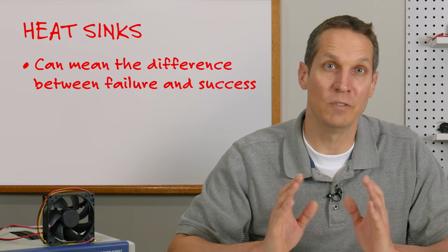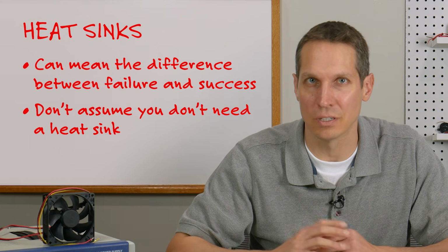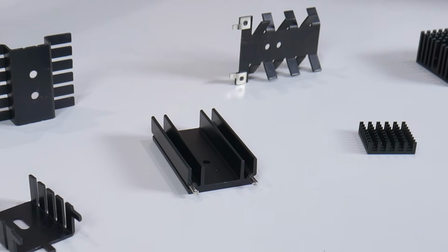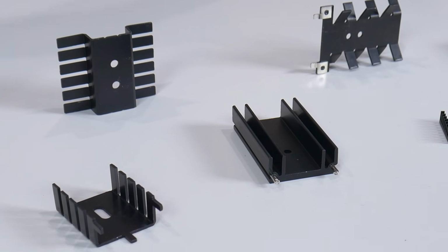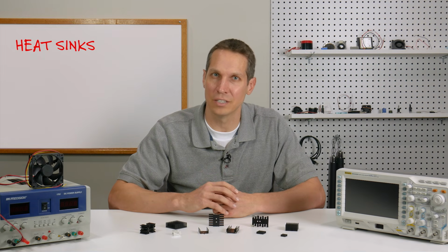Heatsinks can be the difference between failure and success, and if you don't need a heatsink, don't just make that assumption. Running the numbers on whether or not you need a heatsink is a straightforward process whose most time-consuming step is finding those values from datasheets, and you will greatly increase your peace of mind if you do the calculations.